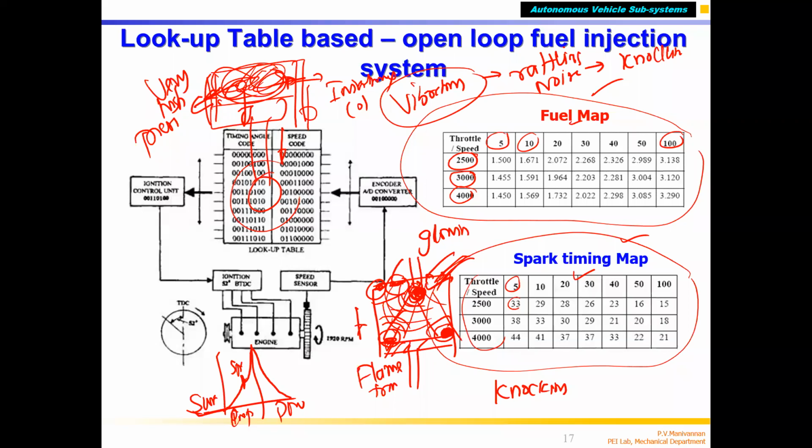Because combustion starts in multiple places, the flame propagates from many points. Instead of starting from one place, the spark plug, and propagating linearly as a smooth combustion that takes a few milliseconds, the flame starts from multiple places. That means all the fuel inside the combustion chamber is burned quickly, within 1 or 2 milliseconds.